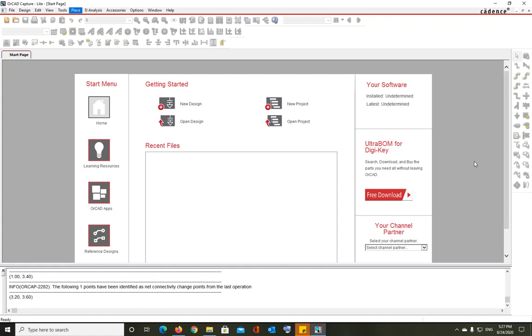So once you design your circuit, you design your project where you have your circuit, and then you create the simulation, and once you run the simulation, then PSpice is going to run. It is going to open the PSpice window and it will show you your simulation results. Basically here I'm going to introduce Orcad Capture, and you have to click on the Orcad Capture light version. If you don't have the full version, the one that I put on canvas is the light version, and you can also download the light version from the Cadence website.